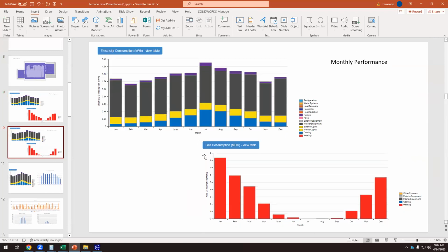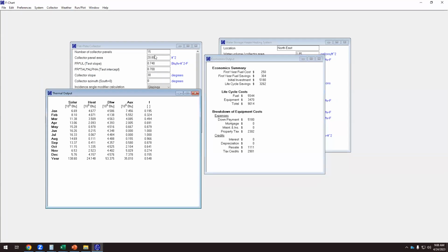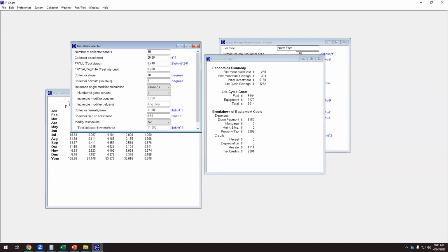Okay, so that means that here, if this is the gas consumption in January, we can reduce this 15-20% with all these elements that we have used. The F value is more than 1 in summer, because in summer we don't have any heating demand. We have a hot water demand because that's steady throughout the year, but the heating, we don't have any heating in July and August.